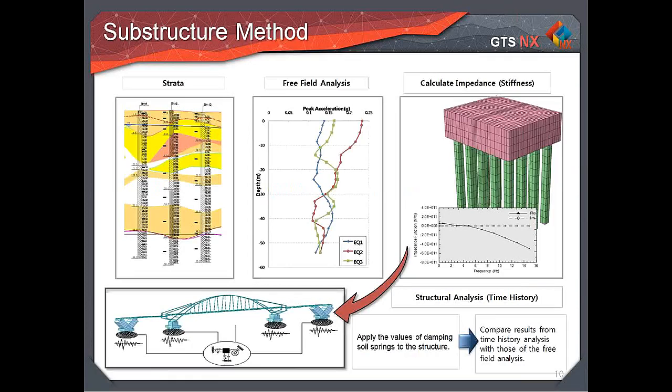The typical process would be, one, to take some boreholes at the site to get information about the strata of the site of interest. In this case, we see that there were 3 boreholes at the site. Let's assume there's a structure that's going to be placed in the middle. And so we get this information about how the soil is distributed underneath. And we can already see here in the middle there's a pocket of some different kind of soil. We're not entirely sure of the properties, let's assume here, or how it's going to affect the structure.